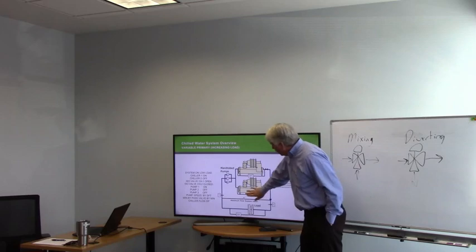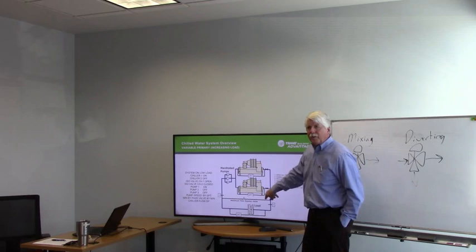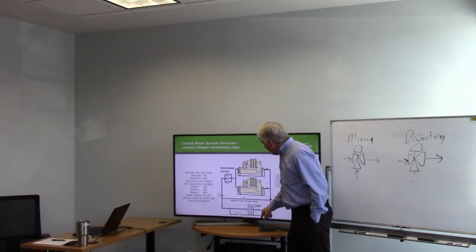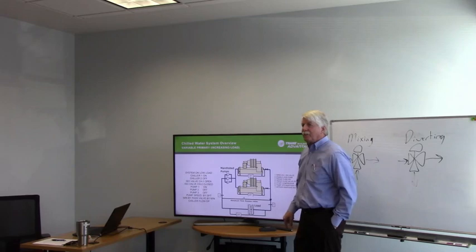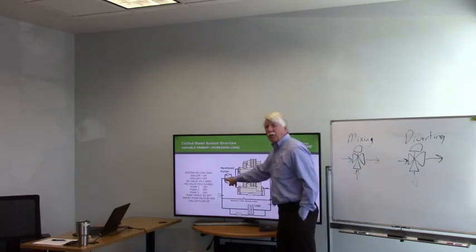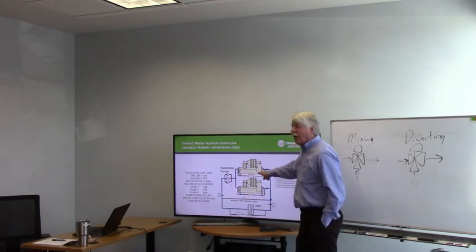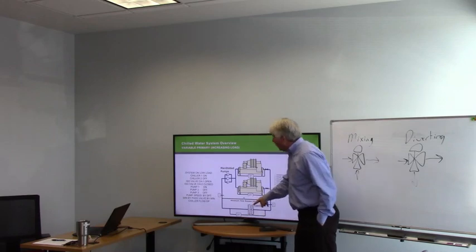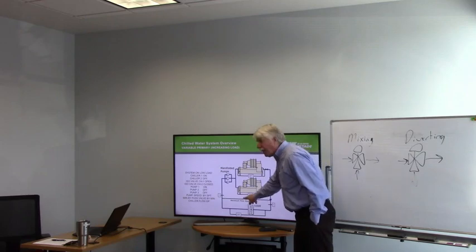All right. Now what happens if our load drops and this bypass opens up? Okay? Let's say we're running along, this valve is closed, everybody's happy. And somebody turns off a gigantic air handler out in the system. And the valve on that air handler goes closed. Okay? Suddenly, our GPM is going to go way down, right? Now, when this GPM goes down, what's going to happen? Your DP will go down. This DP will go down, but more importantly, the first thing this needs to do is protect the chiller. So this valve has to open.